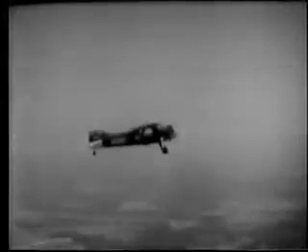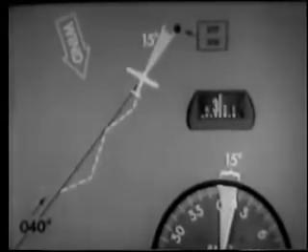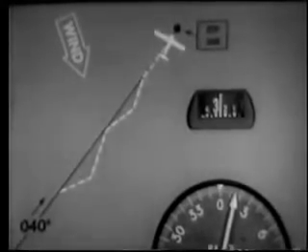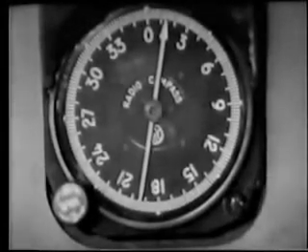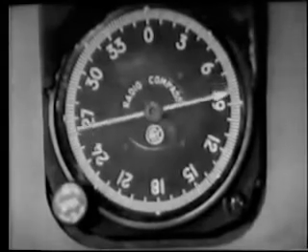Tracking is relatively simple if all procedures are followed. In almost all cases, it is essential that we follow a specific track. Here again is our flight. The 15-degree left correction is making good our track. Let's see how the needle reacts as we approach and pass over the station. The ADF indicator begins to oscillate, and as we pass the station, the needle swings around 180 degrees.